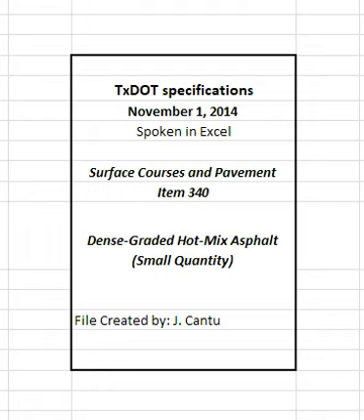Table 4. Maximum allowable amounts of RAP. See table in specifications. One must also meet the recycled binder to total binder ratio shown in Table 5. Note 2: up to 5% RAS may be used separately or as a replacement for fractionated RAP. Note 3: unfractionated RAP may not be combined with fractionated RAP or RAS.